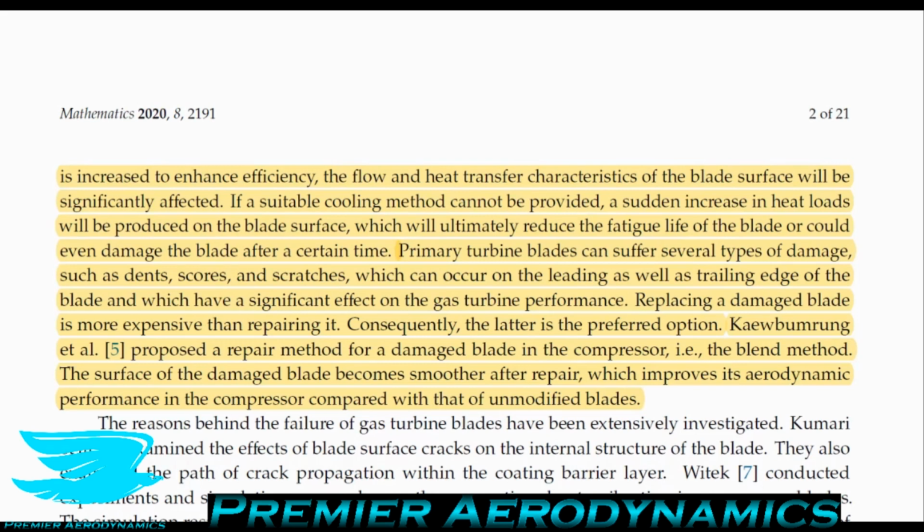And it's actually really cool how they can make blades. Now technology is really advanced, where they're doing 3D printing of blades, but historically they would often make blades out of one crystal. If you look at a metal, for example, there are things called dislocations in the metal, and this is where the molecules inside the metal are obviously linked, but sometimes you get defects where these molecules are not linked. These are called dislocations, and these are effectively fault lines where the blade can expand along that zone.